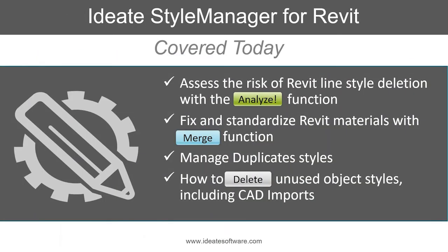So real quickly, I just showed you an analyze function of Ideate Style Manager. We talked about how we can merge from a non-standard style to an approved style within our project, and showing you the different colors will show you duplicate styles or the same definitions. And then we were able to delete those either unused object styles, or like in this case, we went through and deleted some imports in the CAD files.